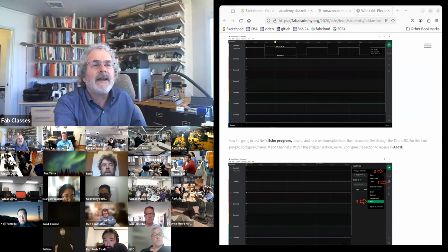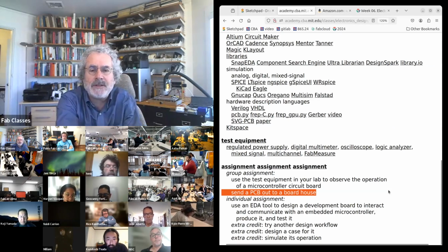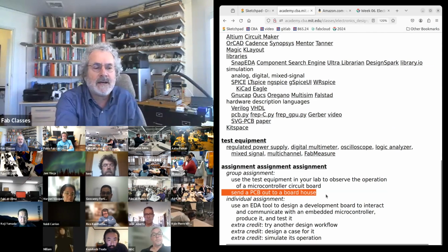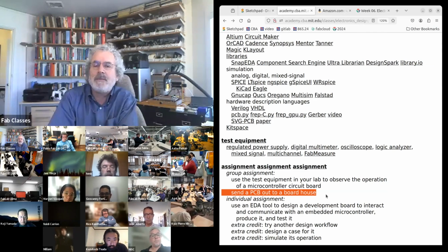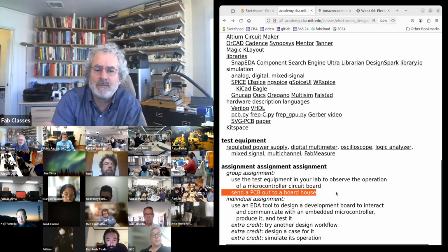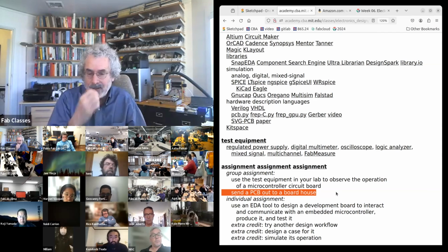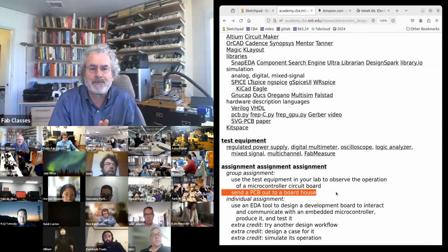And the last part of the group assignment, and this one is suggested for this week, but I just want you to do it at some point in the cycle, is now that you're designing PCBs, pick a PCB that's hard to fabricate in-house and go through the steps of producing the Gerber and sending it to a board house. You don't need to do that for everybody's boards, but I want you to see how to do that as a group.